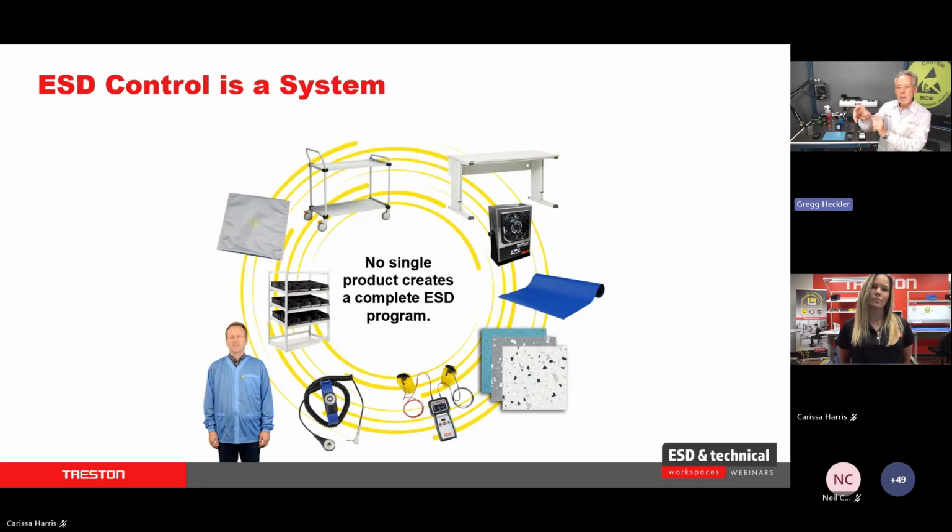By the way, a wrist strap is not the band only. A wrist strap is the band and the cord, and then it's tested with you in that system. So you're not just measuring the wrist strap, you're making sure your human body is grounded properly. That's how this wheel that you're seeing here, with multiple components from flooring to ionization, all combine to make 100% of a static control program. That's the important thing. All of these things are based on how sensitive the device is. And today we have components that are less than 10 volts, or even less than that now.